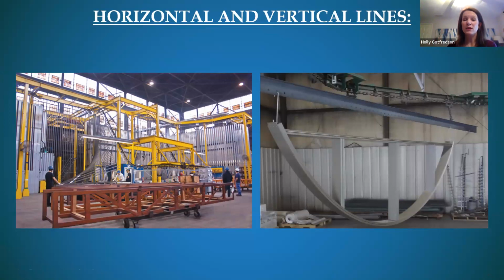And something I'll mention here also is, let's say, for example, you have one color for your entire project and you're getting your extrusions painted at a vertical line, you're getting everything else painted at a horizontal line, and you have an extrusion that's being put next to, let's say, brake metal, and the color looks slightly different, even though they're the same color. That's because the processes are different. That's called pigment flop.